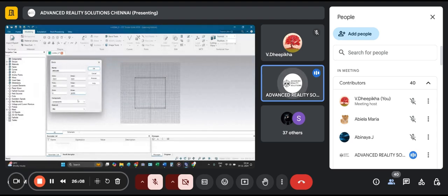I am telling this because whatever value you enter during the simulation process, you should justify it. You cannot put random values here. So please pay attention in this ground layer design. Look at the x and y values. Their minimum value will have minus values, but the z value will never have a minus value. Please keep in mind, the z minimum value will never go to the negative region. Okay, so this is the set of values that we should enter.